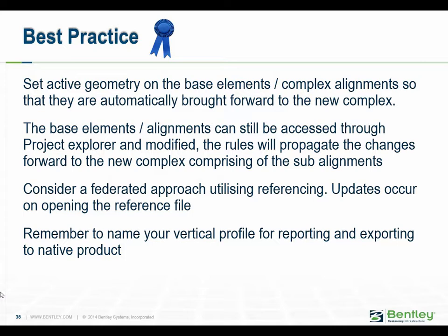With a profile, if we have an active profile on an element, when we create a complex it brings that instance forward and makes it available for us to use, but we do not get the manipulators on it. So you have to navigate down, and that's where Project Explorer assists you. You can navigate down to the original element, open that up and profile it. This helps in situations where we're working across reference files, because the reference file will contain the original profile that we may need to edit. So be aware that you may need to navigate through some of these reference files to manage those edits.